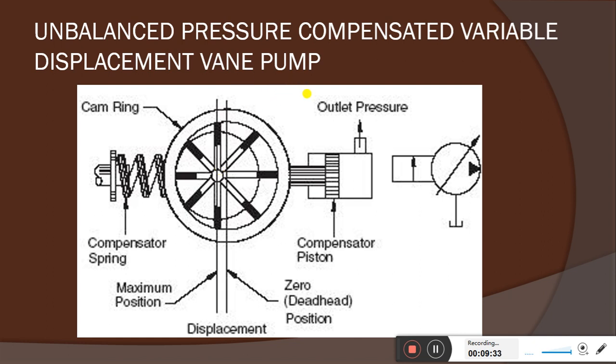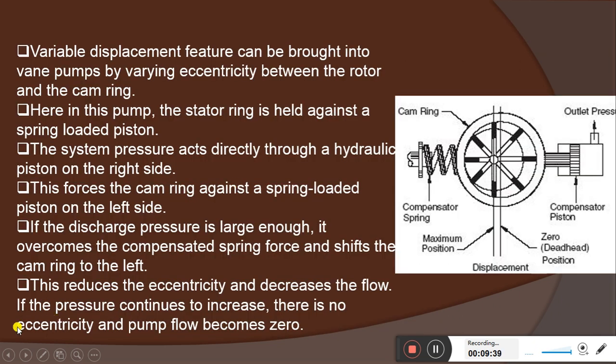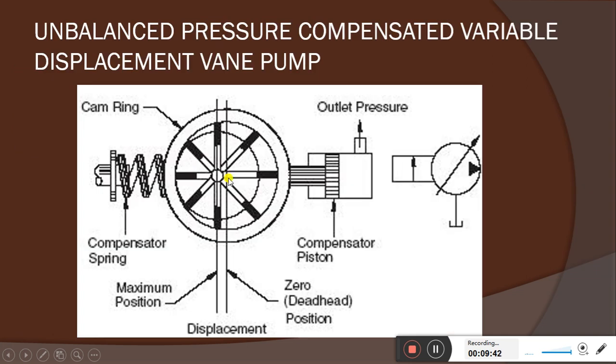To avoid that, we require pressure compensation, because if you experience higher pressure it should be reduced so that it does not affect the pump action. With pressure compensation you can protect the pump, and it can be operated for a longer term. That is one of the advantages.